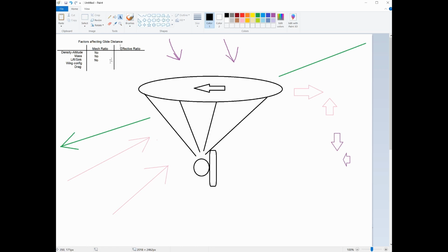Now here we get into the wing configuration. So we have our speed bar, which would pull the front of the wing down. And then we have our trimmer system that we can let out, open up, and lengthen the rear. So that, in a way, would rotate the wing like this, just to visualize it. And that's going to change your angle of attack and change the characteristic of the glider. So this does mechanically change the glider.